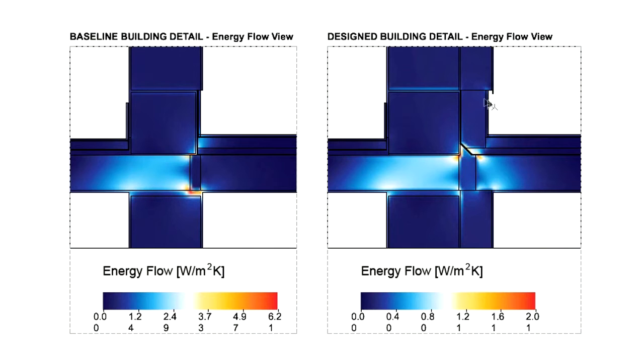It is recommended to perform the thermal bridge analysis on all critical details of the building project in order to incorporate the results in the overall building energy calculations, and also to avoid local thermal comfort issues as well as condensation problems.